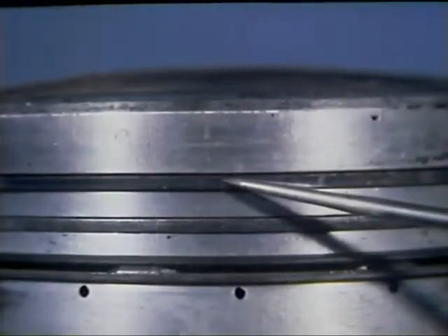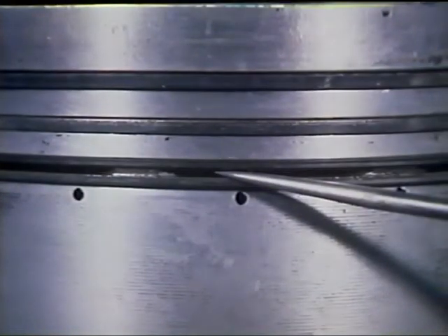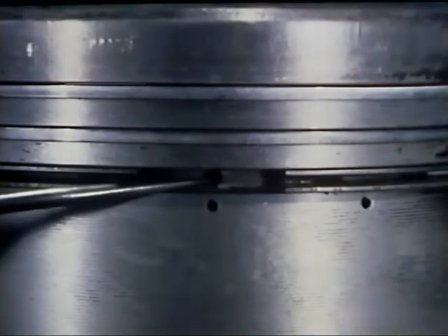Cast iron compression rings are fitted into the top grooves of the piston. This provides a seal for the transfer of heat from the piston to the cylinder. An oil control ring is also fitted into the groove below the compression rings. This ring controls the amount of lubrication between the piston and the cylinder wall. Holes are normally drilled through the piston in the oil control ring groove. This allows the excess oil to drain back inside the piston.